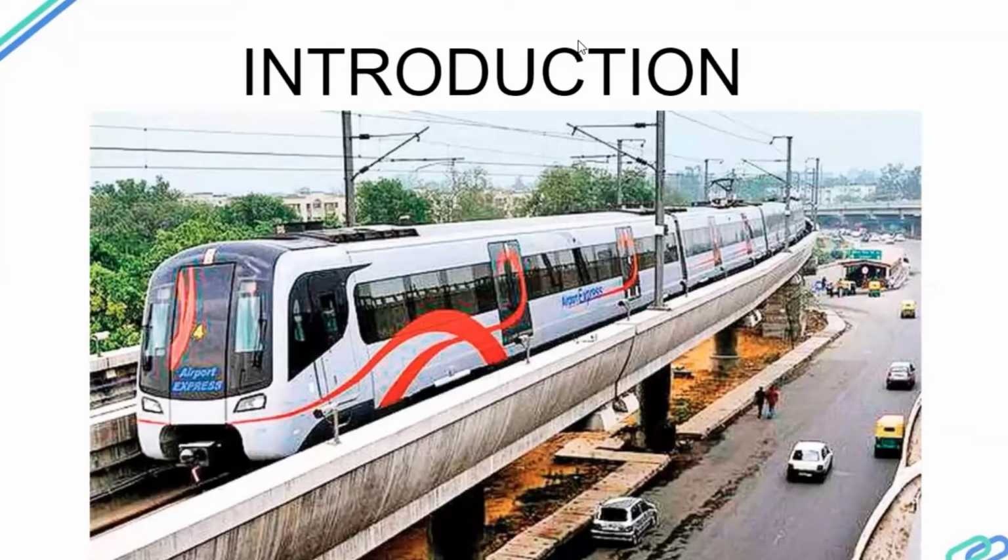Starting from the metro itself, we see the superstructure, the part which takes directly the load of the metro. It is a U type of structure. This is one of the very famous options that are being used nowadays by metro authorities, because it is a lightweight structure and it is a precast structure.